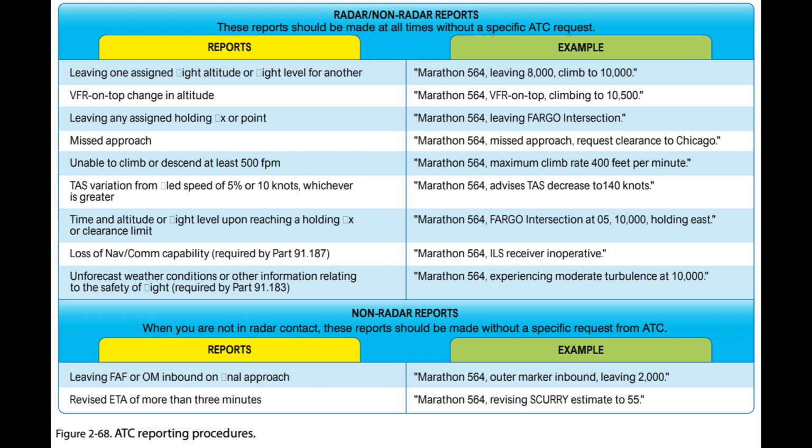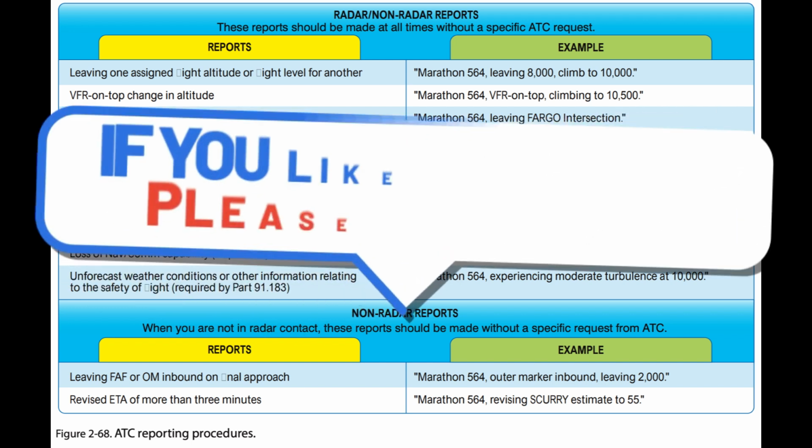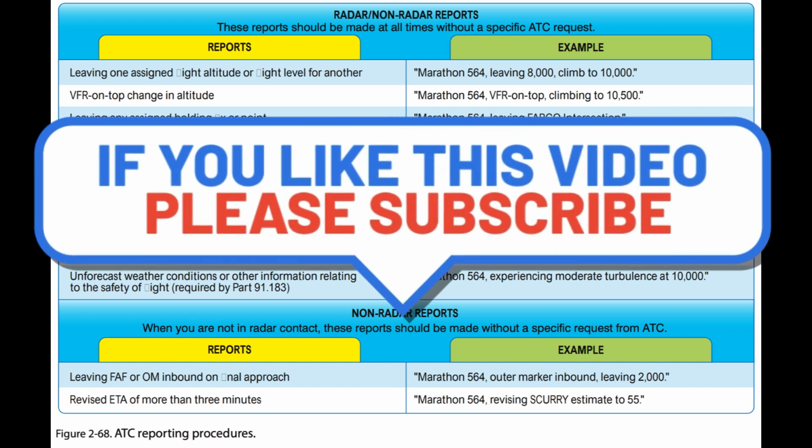When a position report is to be made passing a VOR radio facility, the time reported should be the time at which the first complete reversal of the TO/FROM indicator is accomplished. When a position report is made passing a facility by means of an airborne ADF, the time reported should be the time at which the indicator makes a complete reversal.